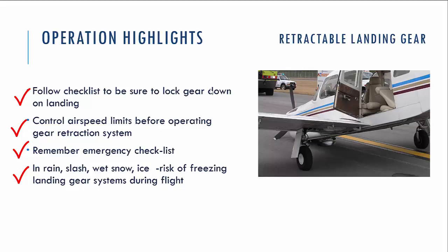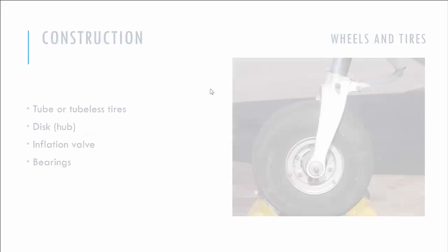So you need to make sure that landing gears are cleaned of slushy snow, for example, by retracting and extending landing gears twice. So let's turn now to the construction of wheels and tires.